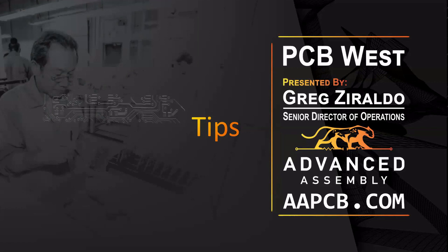If this is something that you guys are going to be working on with heavy copper, you should probably be starting to have long conversations with your PCB manufacturers, engineering departments. Regardless of the size of your board, heavy copper is going to be a challenge really for anybody, depending on your design. And small, seemingly insignificant design decisions can lead to huge cost spikes. Again, like I said, latent defects or boards that just don't meet your design requirements.